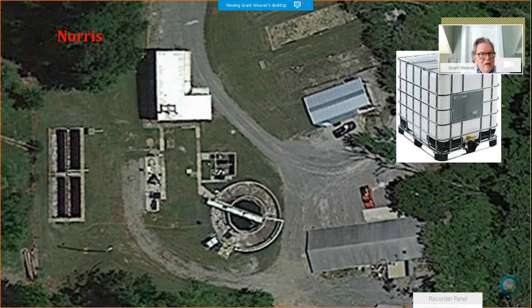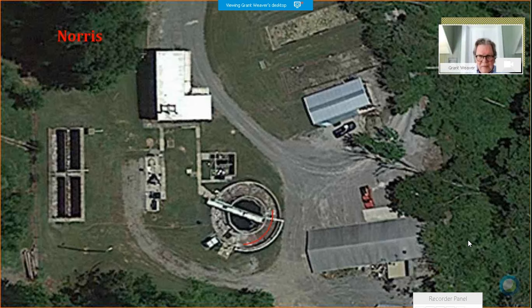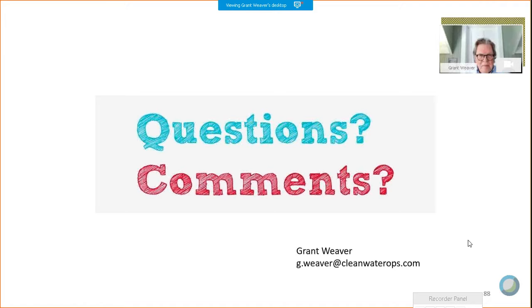septic. If it goes septic, it creates volatile fatty acids. Because there's mixed liquor and phosphorus removing bacteria in there, they are consuming the volatile fatty acids. And then as they're released back into the aeration tank, they're taking up the phosphorus. So there's a $100 fix that to date has cut their phosphorus in half. Hence the governor's award.